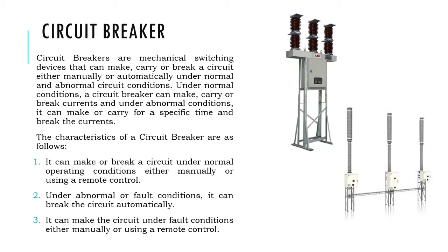In that, there is some deep depth. The literature or explanation of the breaker will be in depth. Each and everything: what type tests are to be conducted, how they are to be conducted, and what IEEE or IEC standards we have to comply with.